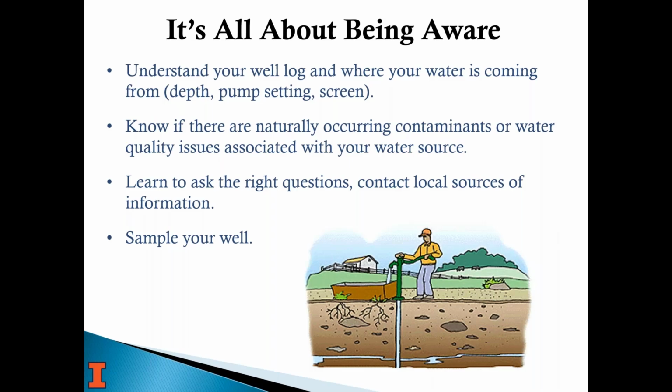There's a lot of other things. It's really meant to be a way to identify if your well has any issues as far as leakage near the ground surface. And then also sample every 3 to 5 years for inorganics, metals, all the things, just to have a good understanding of what your water quality is.